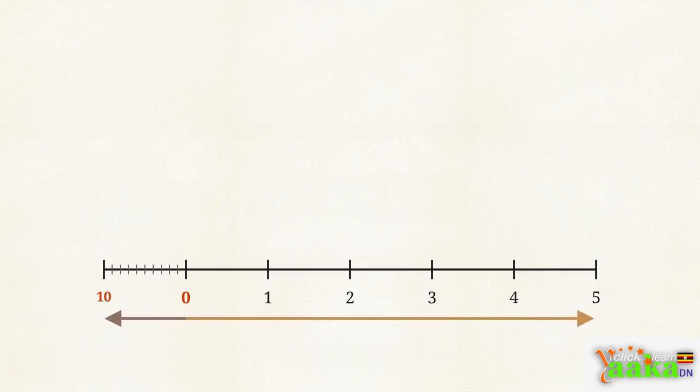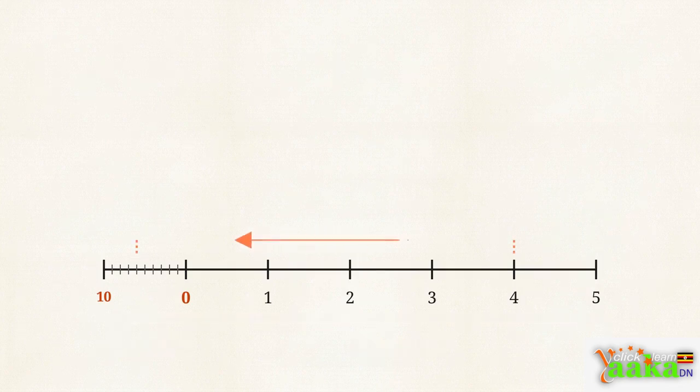Looking at this layout, where would you place your marks to show exactly 4.6 meters? Placing the 0 mark internally is the only way a single flat line can measure whole units in one direction and decimal subdivisions in the other. To plot 4.6, count 4 major divisions right of 0, then count 6 minor subdivisions left. The total span is 4.6 meters.